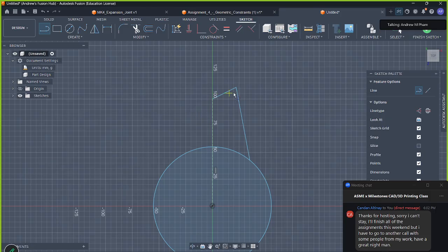Like let's say in this case, I didn't want it to be horizontal, and I drew it pretty close to horizontal, and then it snaps to horizontal, right? In this case I did want that, but sometimes it might be undesirable, where it'll give you a constraint that you didn't want, or sometimes it won't give you the constraint that you were assuming that it gave you, right?